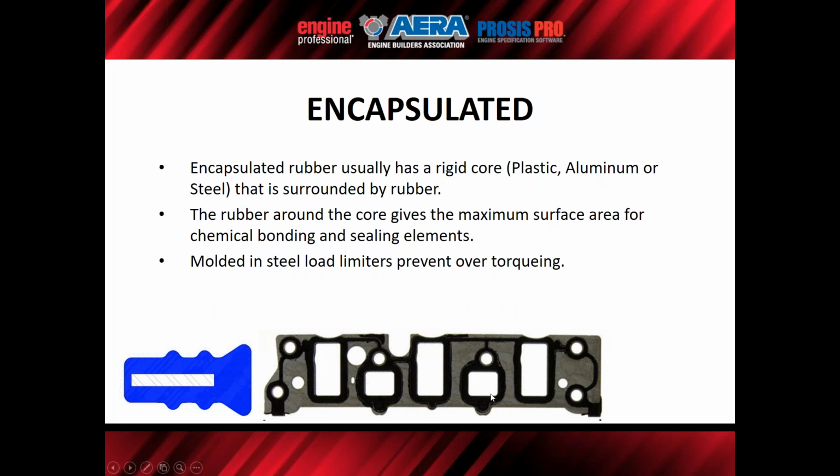This particular gasket has a specifically blended elastomer for the OAT environment. So it's specifically designed to handle the OAT coolants. I'm not sure if the competition has that or not. If it doesn't, it's usually a Viton, which is really good in coolants or fuel mixtures. Just like this one is a Viton, but it's a specifically blended one for OAT.